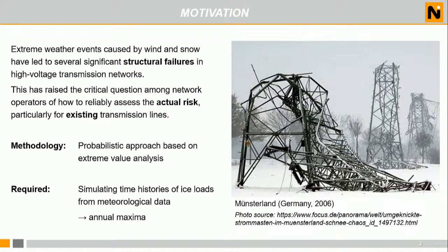And the best approach to estimate the actual risk is a probabilistic approach based on an extreme value analysis. But for that, you need to simulate time histories of ice loads based on meteorological data. And if you're able to do that, then you can calculate annual maxima and do your analysis. But the link between meteorological data and time histories of ice load is the missing link that we have tried to investigate with this project.